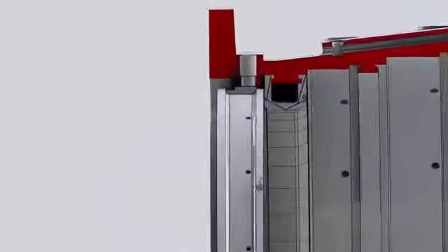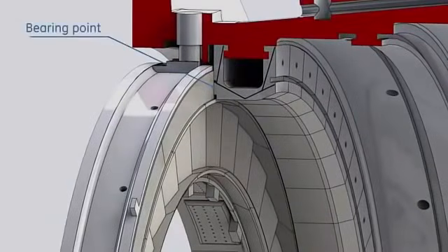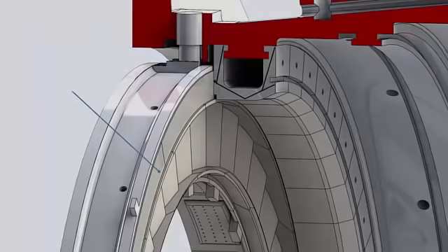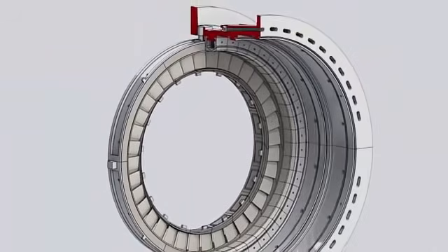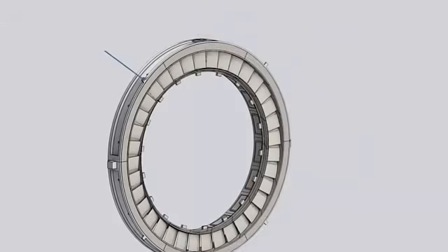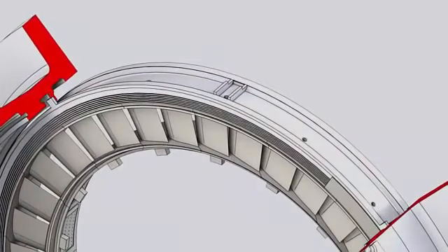The aft outer face of the retaining ring is loaded against the forward face of the first stage shroud, with seal strips in between to prevent compressor discharge air leakage between the nozzle and the shell. The nozzle 1 assembly is prevented from moving forward by 4 lugs extruding from the outside diameter of the retaining ring at 45 degrees from vertical and horizontal center lines. These lugs fit in a groove machined on the turbine shell.